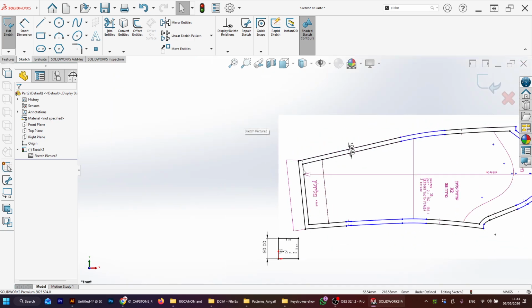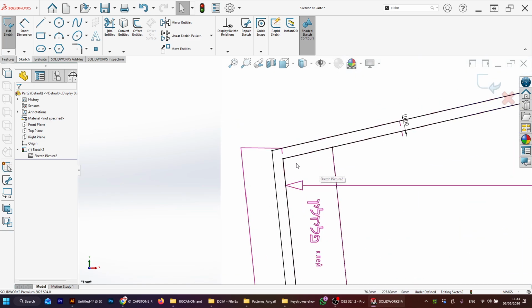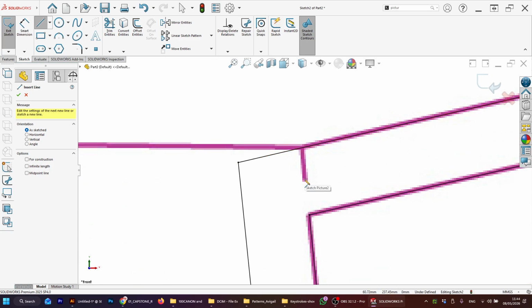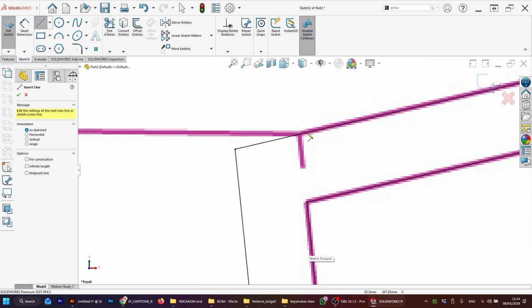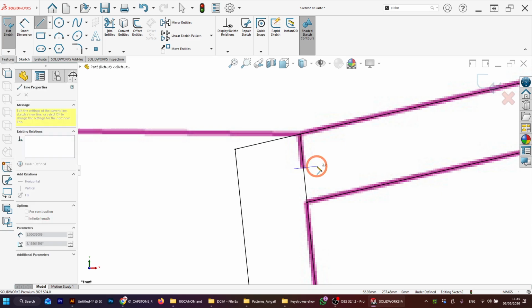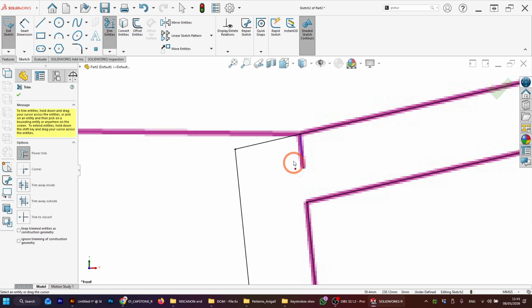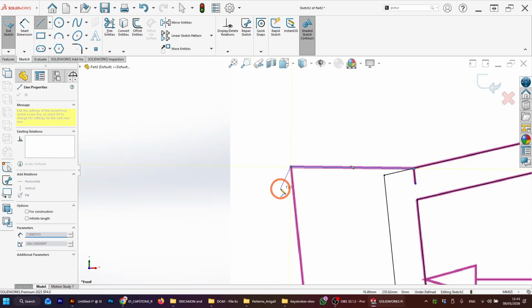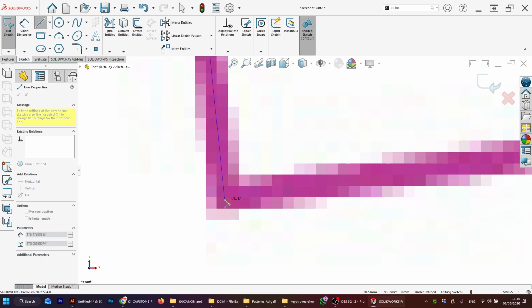And the picking line, we're gonna do it last because now we can really do that easily. It's the same method. I click here on the edge. Actually, if you want to do your picking line now, because maybe the picking line is the extension of that, I can use extend, click. So now I have this line. If I want to shorten it, that's where I need to use a little trick: I put a line across and use trim to cut them both. That's slightly different from Illustrator, where it would be easier to do that. Here I have to do it that way. But at least now I know that this point is perfectly placed. So I can continue to sketch from here, go till the end, go down, and play with the wheel to zoom in, zoom out.